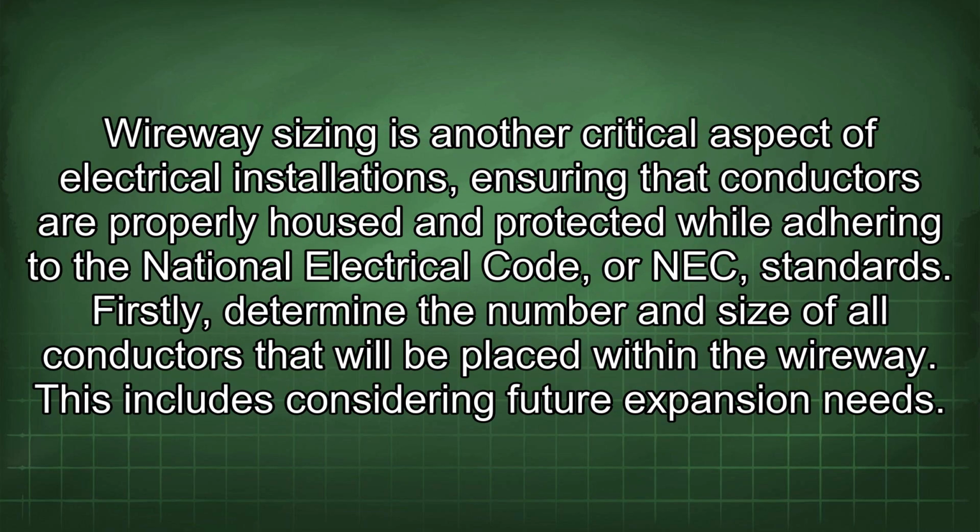Wireway sizing is another critical aspect of electrical installations, ensuring that conductors are properly housed and protected while adhering to the National Electrical Code, or NEC standards. Firstly, determine the number and size of all conductors that will be placed within the wireway. This includes considering future expansion needs.